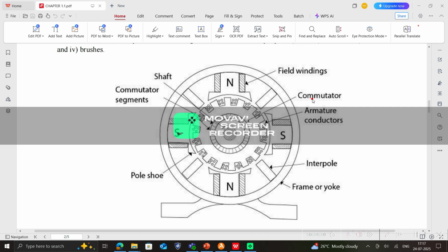Mainly copper conductor is used in the case of the magnetic field, and we have many conductor windings, known as the armature conductors, which are placed on the armature slots. We already know that in any machine the excitation supply is always a DC supply, and field windings are usually for conducting electric current as it is, since it is an electromagnet.